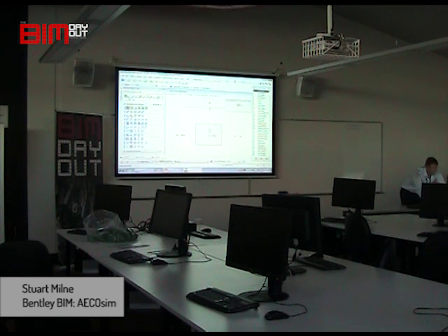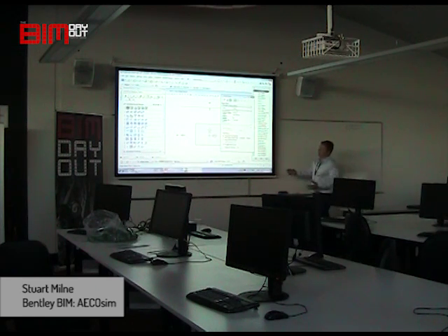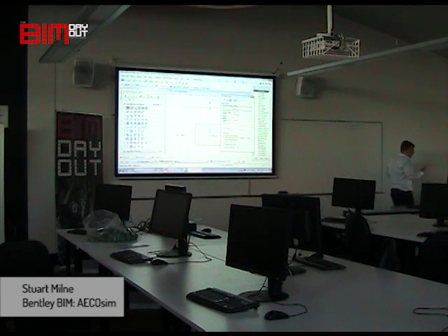You can select that tool and this dialog box appears. It has quite a few settings you could alter. You could give the space a name. You could select a space type from the list, like toilets, bedrooms, whatever. But we'll just go for a generic type at the moment because we don't know what that's going to be, and we'll leave it as is.